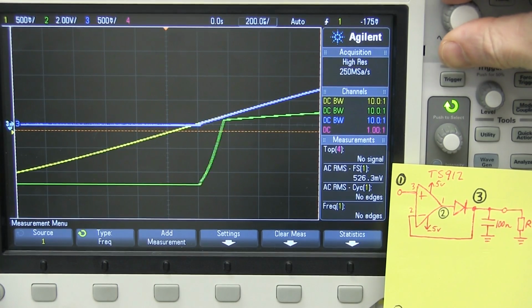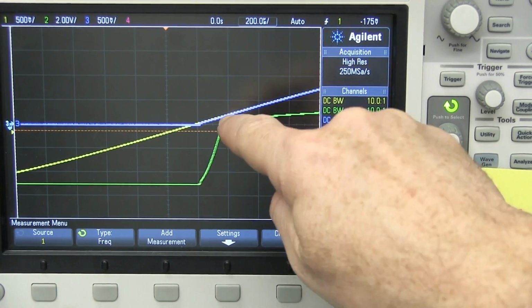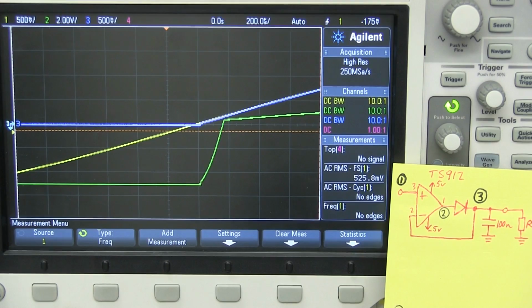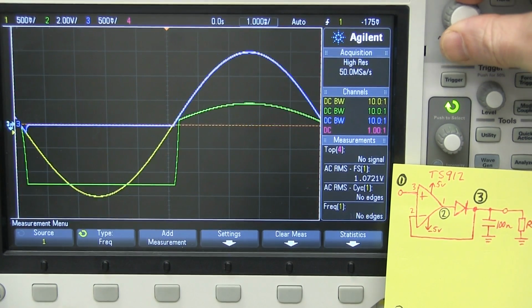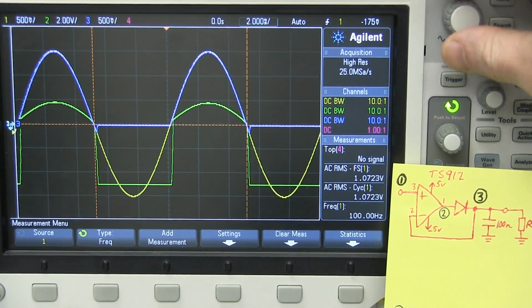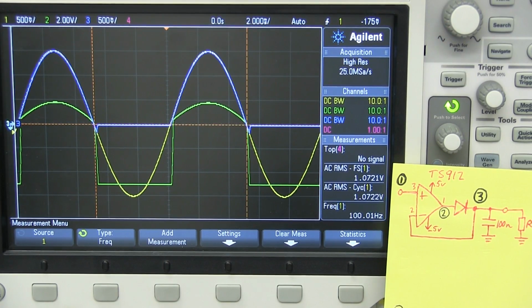won't be able to ramp up instantly. You see that? It can't. You know, the op amp has a certain slew rate. It's got to charge the capacitance, in which case there's no capacitance at the moment. So that's why, even with a 100 hertz waveform, as you can see, low frequencies, we're going to run into a few problems here.